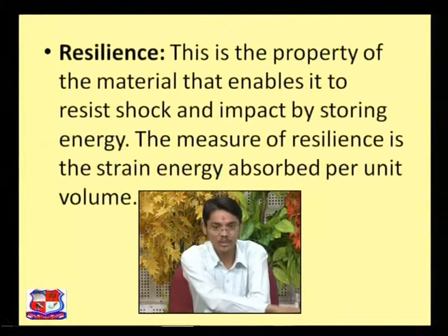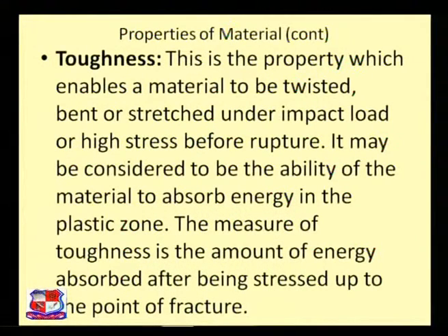Now dear students, we will switch over to toughness. This is the property which enables a material to be twisted, bent or stretched under impact load or high stress before rupture. It may be considered to be the ability of the material to absorb energy in the plastic zone. The measure of toughness is the amount of energy absorbed after being stressed up to the point of fracture, right.